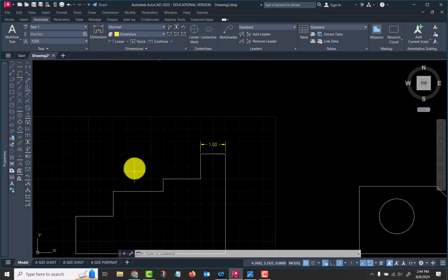And then if you look, we've got what appears to be a continuous line. It's not a continuous line, but it appears that way. And in the textbook, the standards when you're dimensioning to the center of a hole, it should appear that way because the extension line and the center line should become one entity. Okay.